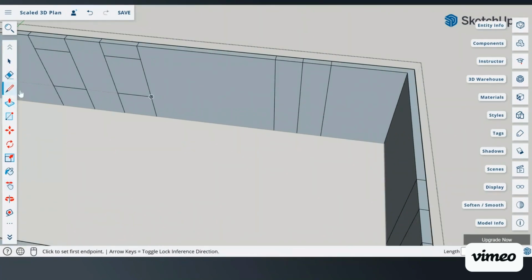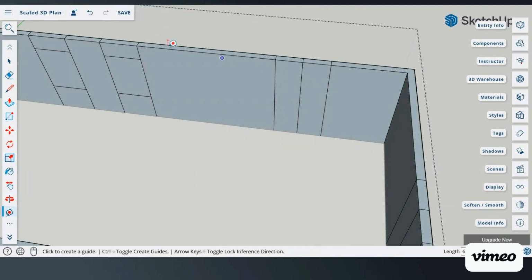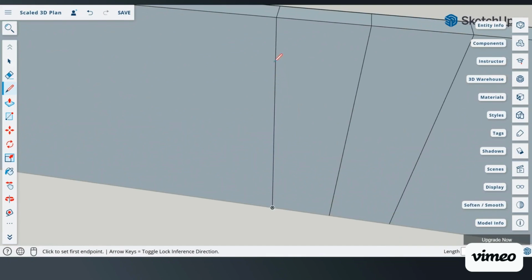For my door, we're going to say our door has a height of 60 inches. So going to the endpoint, I'm going to draft my line, or I can use, again, my tape measure and just say I have a height of 60 inches. So type in 60. Remember to press 60 and then enter, because the default of the program is in inches. So find where that endpoint is. Oh, maybe I was zoomed out too far to find my marker here. That's okay. I'm going to draft my line and type in 60. There we go. It was way down there.